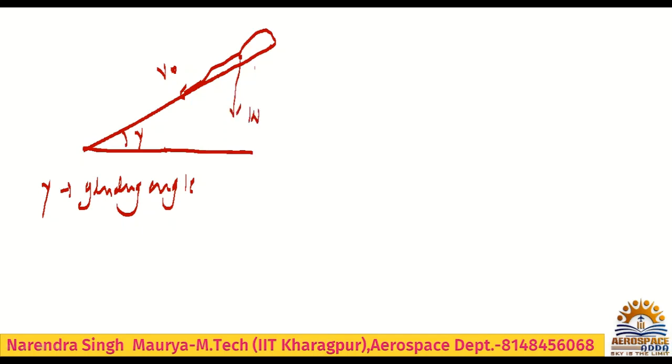So weight is downward, and lift will be perpendicular to the motion. And what will be the drag? It will be opposite to the motion. And here definitely this is gamma, the gliding angle, so this will also be gamma. So this component will be W cos gamma, and on this side, this component will be W sin gamma. Yes or no?